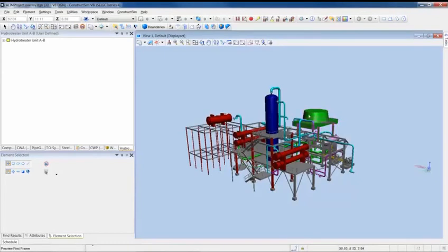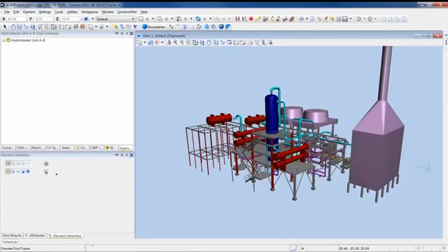If we cast our mind back to the pipe we identified earlier, we can now see that it is being connected to one of the fans, and we may need to adjust this installation sequence. So, in this quick example, we've highlighted 2 separate issues, and we can now decide a plan of action. We can either modify the schedule inside of the software and rerun this to validate what we have done is correct, or inform the planning team so they can address it in Primavera.